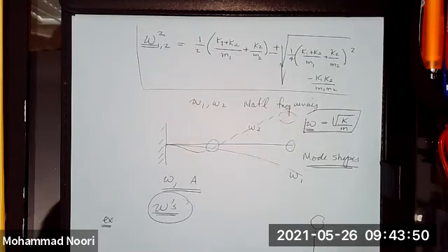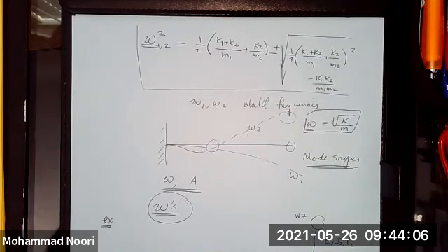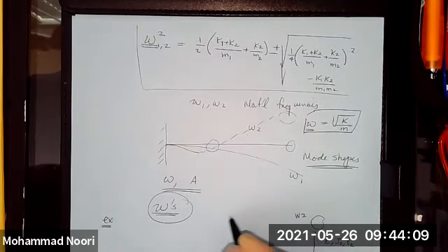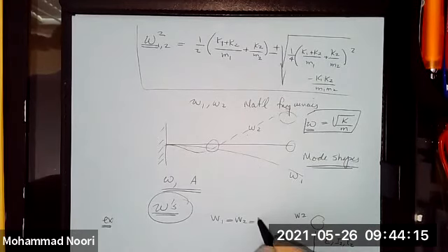I will use that same example of that building where this was W2, this was W1. The material and geometric characteristics of each column are given. Let's say, to make life easy, assume the two weights are equal. In other words, the two masses, M1 and M2, would be equal, W over g. I1 is equal to 2I, the I2.